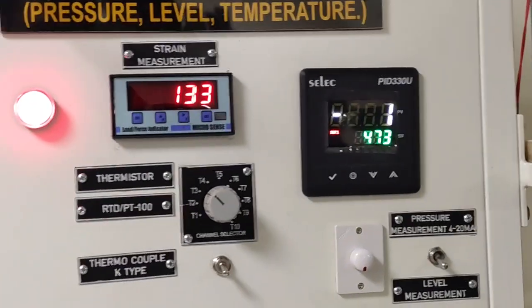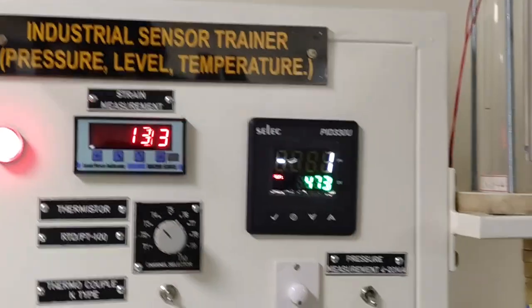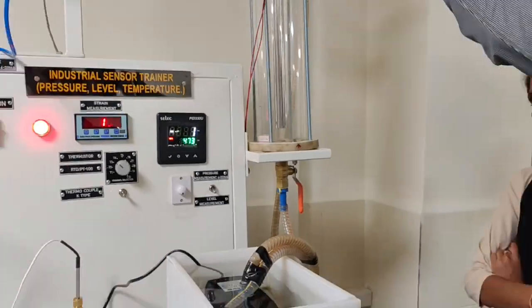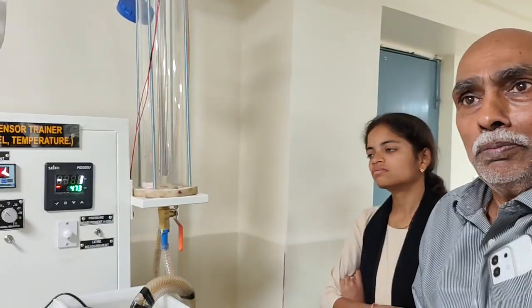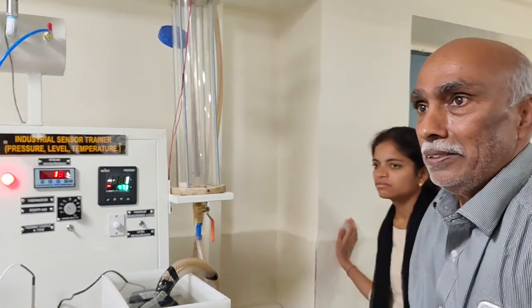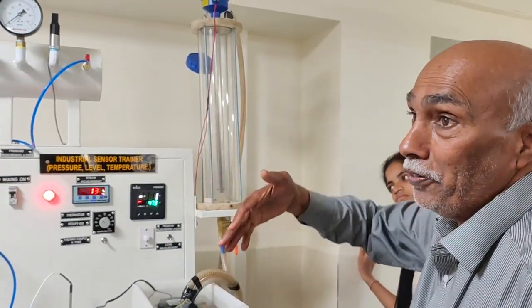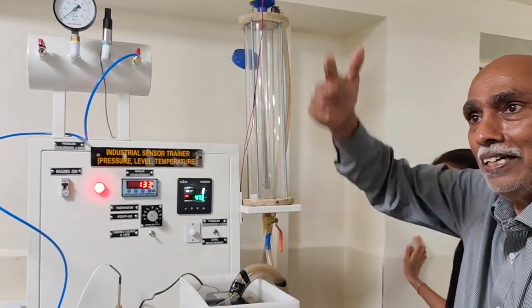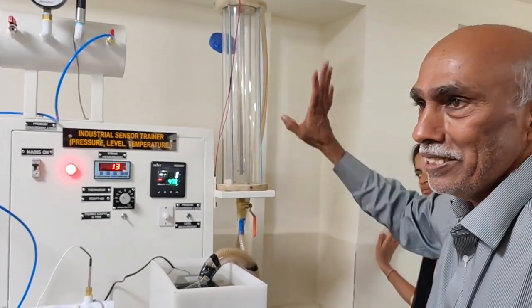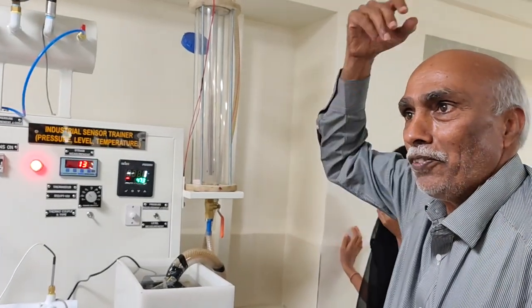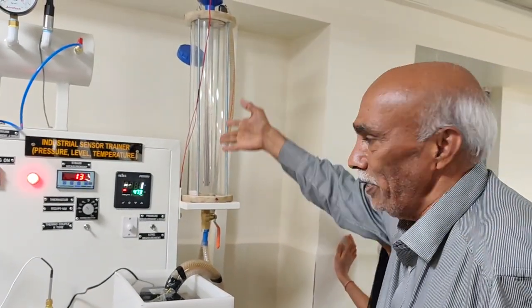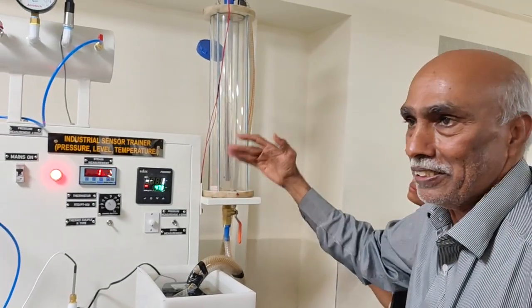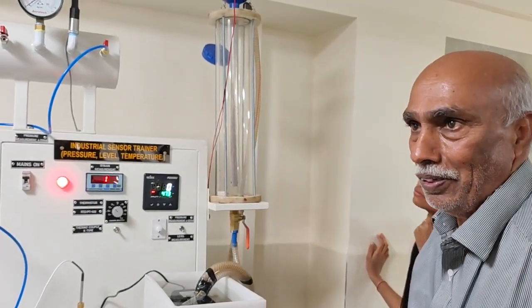The concept is why this has to be selected. See, this is only a 400 meter tank. Sometimes your tank will be around 30 meters in height. For 30 meters, you need not go for that much. In the scaling itself, you can increase or decrease the value. 20 milliamps is the same, it won't change. Whether you go for a 30 meter head tank, 2 meter head tank or 1 meter head tank, the cutoff is 20 milliamps, the manufacturer's output current from the sensor.